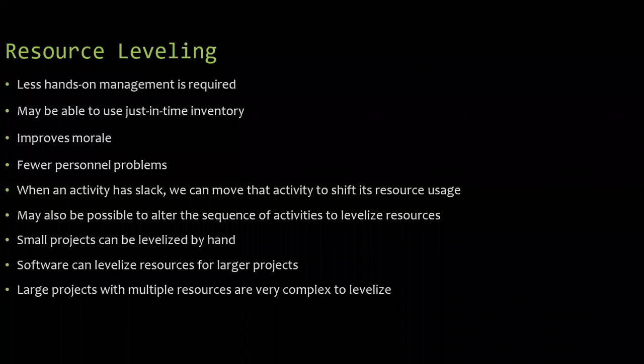When an activity has slack, we cannot shift that activity's resource use. If slack is there, that means that activity is running a little behind time. Then we cannot move that activity to shift the resource. Suppose foundation work is going on and there is slabbing work; we cannot introduce it there if the foundation work is late.